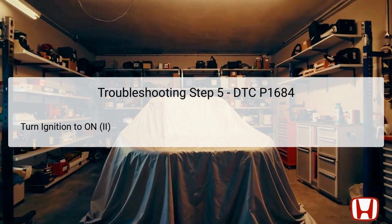Conversely, if the DTC is not present, it might denote an intermittent failure, suggesting that the system is functioning correctly at that moment, leading the technician to check for potential loose connections or poor terminals that could have caused a temporary fault. Checking for available pending or confirmed DTCs is a crucial diagnostic step. If the DTC P1684 appears again at this stage, it's essential to follow through to the next troubleshooting step.